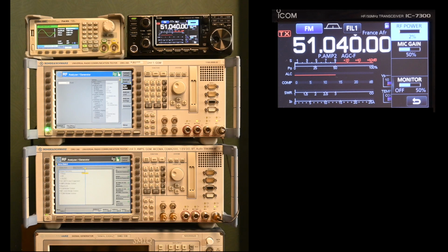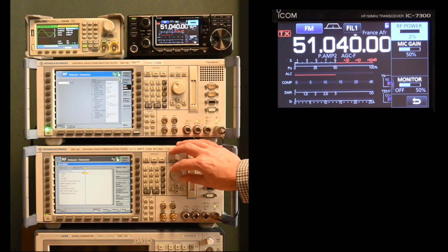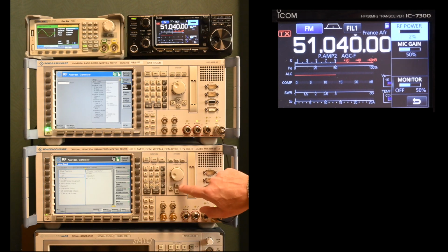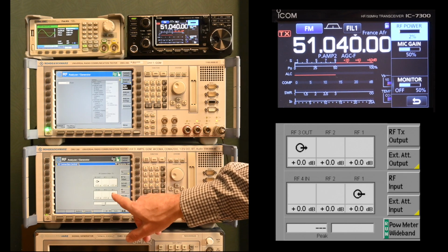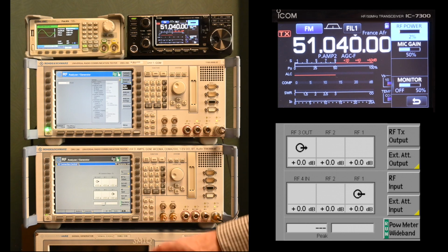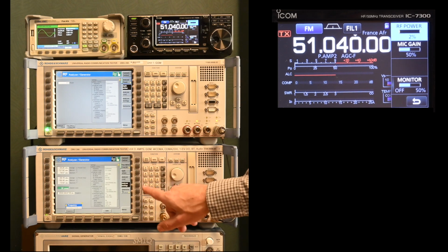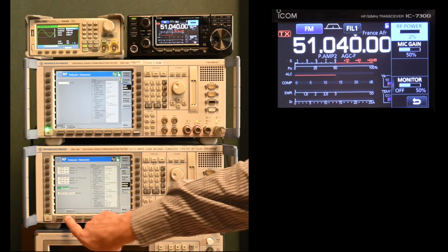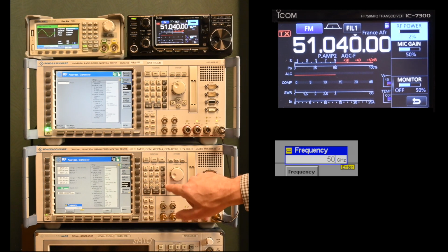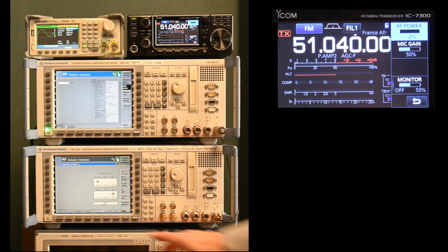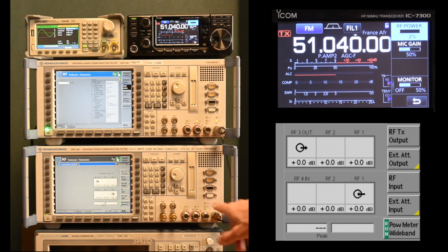Okay, let's look at this unit here, the 2 watts unit. Again, I'll go to the right functionality here. So I'll go to the analyzer menu. I arrive in the startup. It's already RF1 being selected. And like with the other unit, let me just set it to the right frequency here, like is recommended. I'm going back here. I got it connected to RF1. I see the right input here.